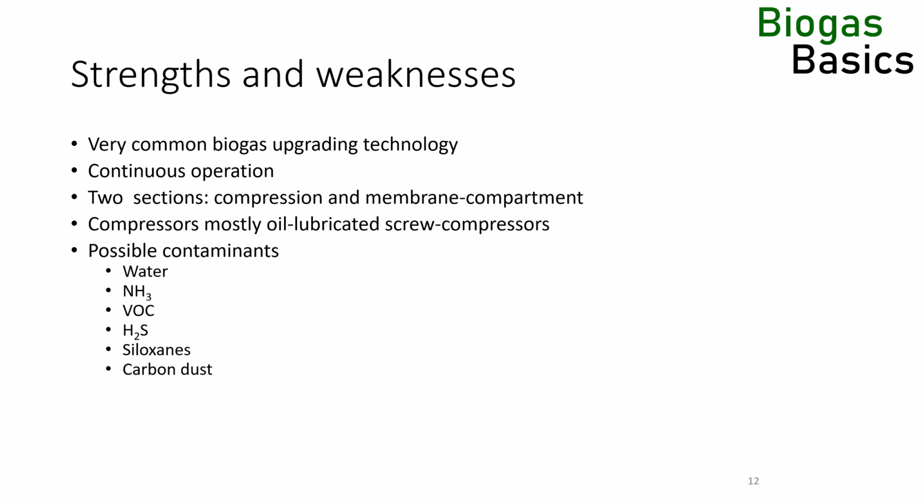When the biogas upgrader experiences an emergency shutdown, it can quickly depressurize, which can lead to the fluidization of the carbon filter and to pressure surges that can propel carbon dust through the header system. Eventually, the carbon dust ends on the potting resin and blocks the inlet to the hollow fibers.